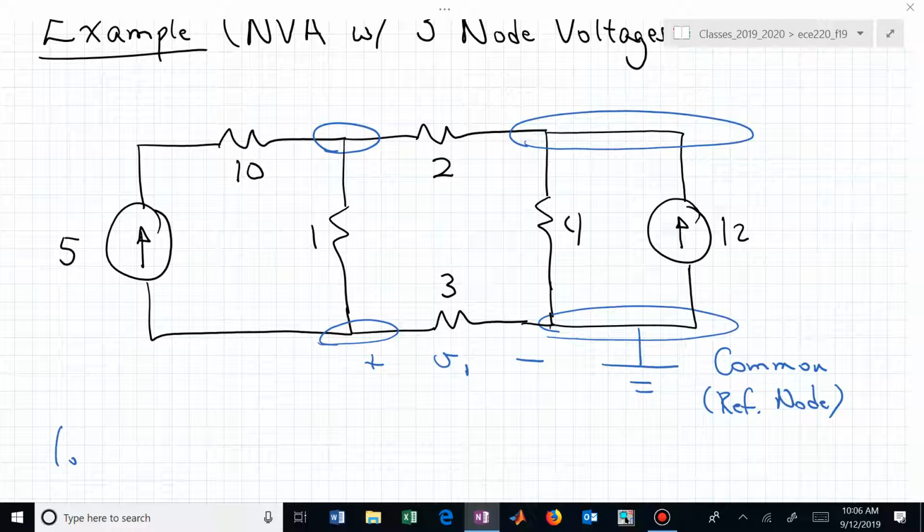The red cable is now where the positive is. It doesn't really matter if you called that one V3 and somebody else called it V2. Well, you can't switch the negatives and positives once you've defined your common node.